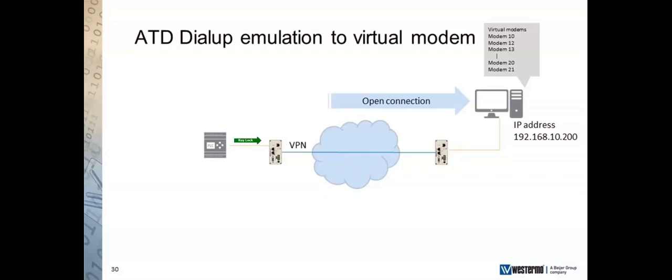So if you want to decrease your scan times on the overall utility system, say you've got 1,000 devices out there and you're not getting round in time using conventional dial-up, by moving to IP, you actually get a benefit in that you can do this dial-up and close calls over 30, 40 lines or 30, 40 connections, if you like, all simultaneously. And because you're cutting out the 30 to 40 milliseconds of negotiation time, everything speeds up within the processing of all the data.